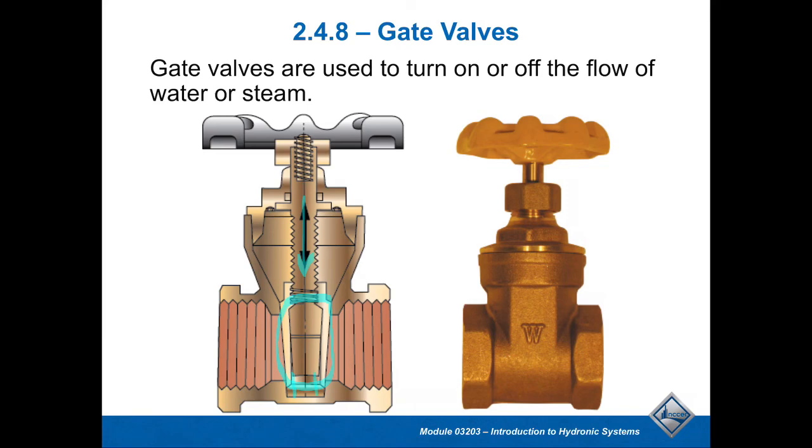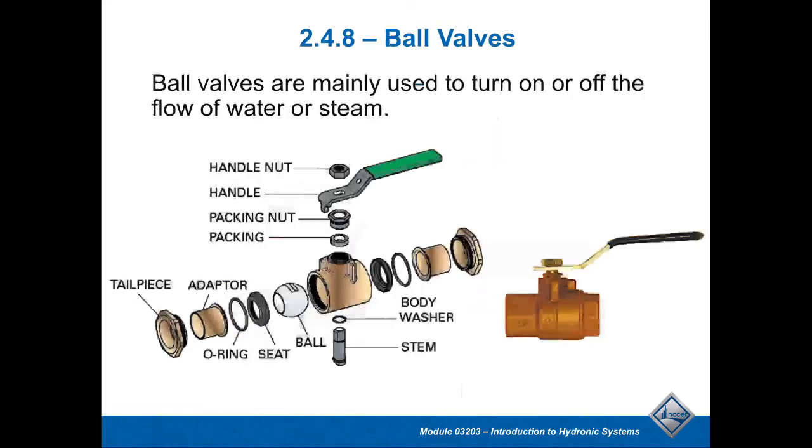They have a disc that's shown right here that would be driven down by a threaded piece, and that little disc will slam down and create a very tight seal. That's kind of one design in there. The downside of these gate valves is that there's really no good way for you to notice whether the valve is open or closed. So that would be maybe a downside of that valve.